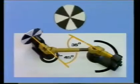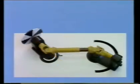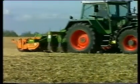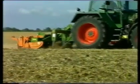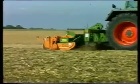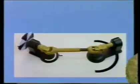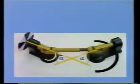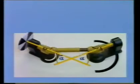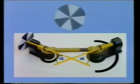When attached correctly, extreme corners can be taken without velocity variation. Together with the drawbar coupling point, the extension of the PTO and PIC forms an intersection. Thus, the working angles of the joints are equal in every position when cornering. The computer calculation shows that right and left-hand corners can be taken with ease.